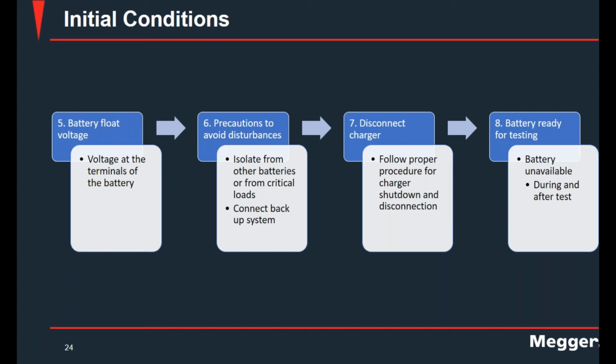And after the test, you probably put the battery back in service. You turn on the charger. But if there's an event right after, in the very few hours after starting the recharge process, your battery is going to have a very low charge and might not be able to go through the events. So you need to consider all of these before running the test, and we are going to see some options for that.